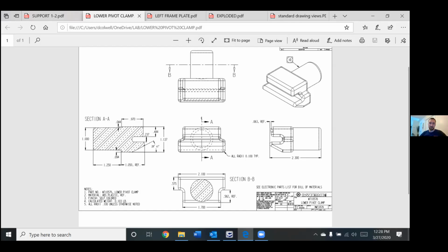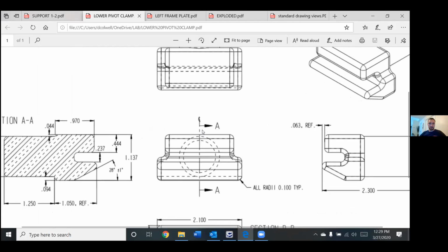And those tangent lines, while I think they help to show what that part would look like from that view, they do kind of clutter it up for dimensioning things to it. So I've created a sectional view where I just have basically an outline, a profile of the part. And I can dimension that without so much clutter in the way. So that's what's happened here. That's the whole reason for this sectional view. And what I did is I cut it exactly on the center line. Let's talk about that center line.